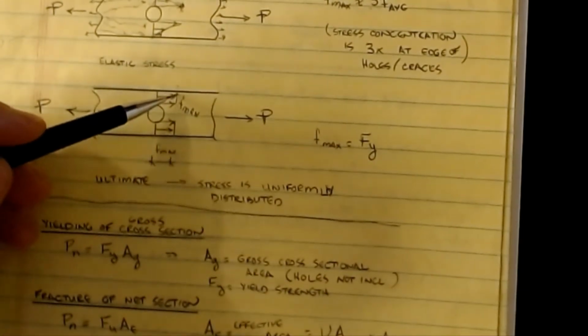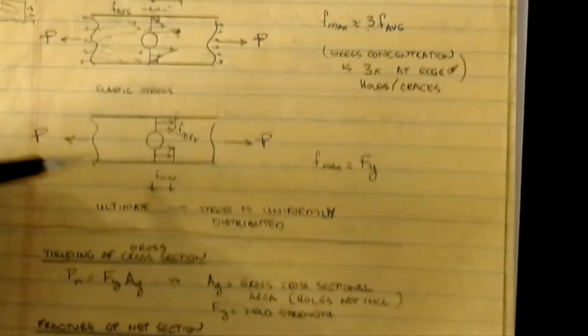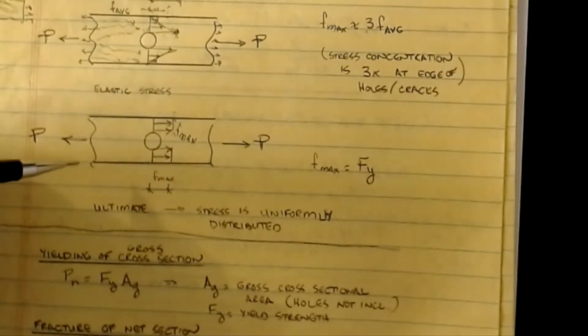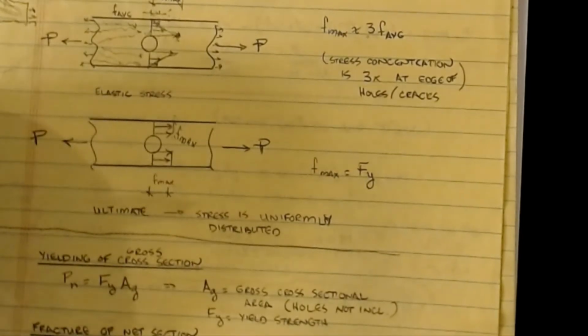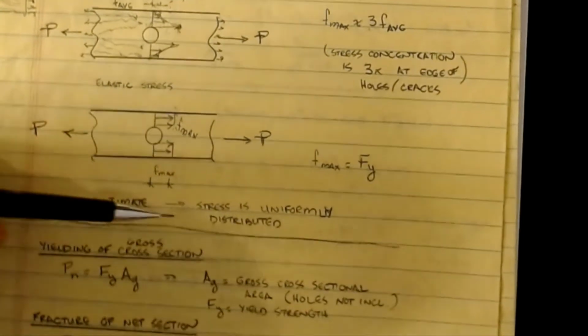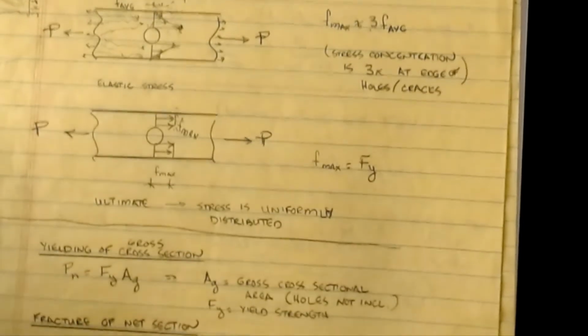Okay, but because I make this assumption, now I've got to correct for this funneling effect that we were talking about with these flow diagrams. And that will lead us to a concept known as shear lag, which we'll get into in our next video. Okay, so there are some rules for how you calculate the amount of the shear lag effect or the concentration that's occurring.